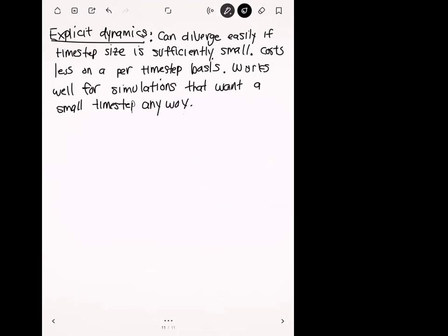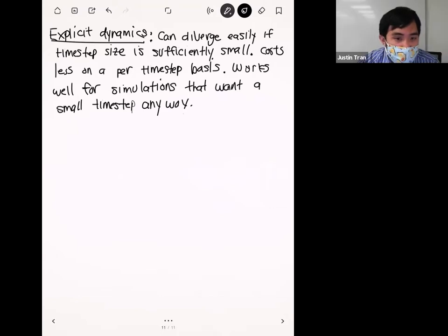Thanks again. Raphael, for the project, are we only allowed to apply loads and boundary conditions that we used on past assignments? No, you can use other stuff. I know people have been using bearing loads and moments, so definitely feel free to use whatever you want. If it's something we haven't covered in the class yet, you might have to do a little bit of research online to see how to properly apply those boundary conditions. The whole repertoire of ANSYS is available to you, as long as it makes physical sense to you.